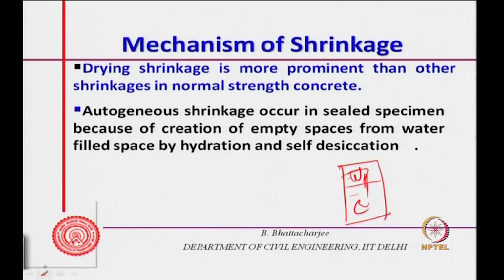Now, let us say this is all a sealed specimen. This water actually reacts and gets consumed, what we call self desiccation, but this leaves some voids in the space, because the water filled space has gone out, and the volume of the hydration product is, as we know, less. This space is not being filled up fully, and therefore it can result in empty spaces, due to the self desiccation process, even if you have sealed it and no water you are replenishing.